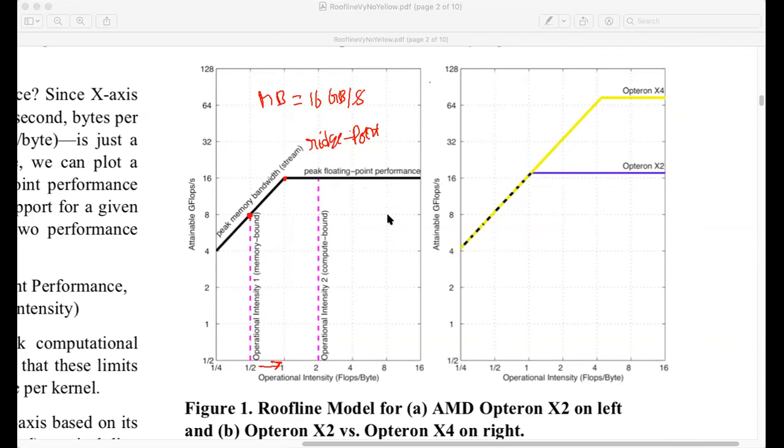So this also helps the processor designers in a way, because if you just keep the memory bandwidth and you just pump up the power of your arithmetic and logic unit, then the application developer has to really struggle. He may not even be able to use all the gigaflops you are providing, because he is seriously constrained by the memory bandwidth.